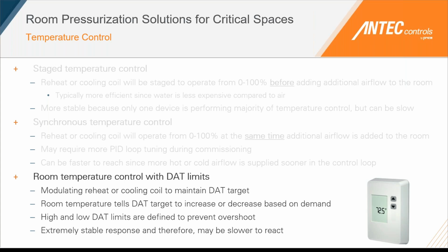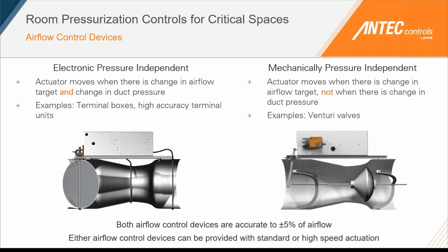Possibly more relevant to the last session, but how long do the position sensors tend to remain accurate? My concerns are mechanical slop or carbon tracking. I'm not confident in 20-year-old Phoenix valves reading accurately, for example. We tend to only certify fume hoods, and they only look for the 100 feet per minute face velocity at sash height, not if the valve CFM matches a particular sash opening. Are retrofit kits available for older Phoenix pneumatic valves, 1990s vintage as well as newer ones? Do they use or replace all the Phoenix components, actuator, position potentiometer?